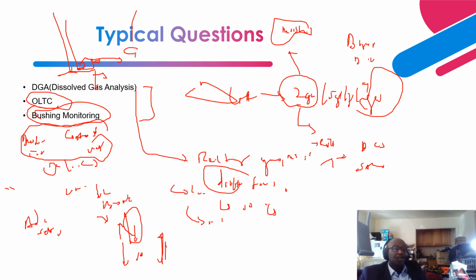So you have a bushing, and you have the conductor here. In between the conductor and this electrode inside the bushing, you have a capacitive layer, C1, and from the electrode to the flange, we have a C2 capacitance, another section. In between that, you have a power factor. This bushing, a condenser type oil impregnated paper bushing, is filled with oil, so it forms a capacitance layer.